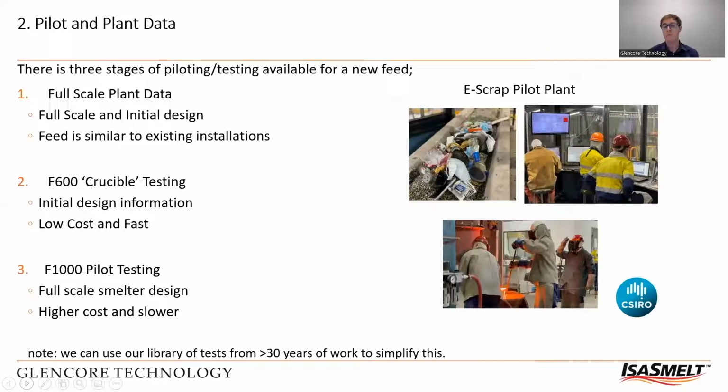After that, when we move to the next phase of the project, there's a higher level of detail required, so we do F1000 pilot testing. This is for your full-scale smelter design. It's generally higher cost and slower than the F600, but this will give you good information on what good refractories to use, what your off-gas system is and how you should handle that, and emissions control techniques.